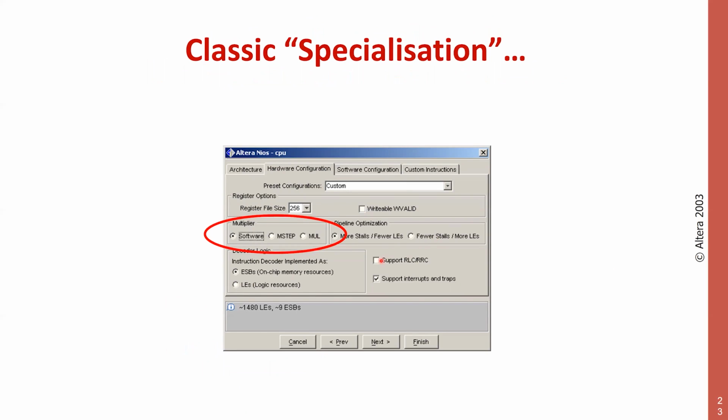And if you take, for instance, NIOS, one of these customizable processors that are meant for FPGAs, in the configuration windows inside the tool, you can say, I want to do multiplication in software, which essentially gives you the code from the beginning. It's very well possible that actually that piece of code I have taken from their library, because then there will be a library in the Altera software that implements it in software. Or I implement this operation, or this operation, which is a normal multiplication, and this one is the intermediate. It's exactly what we have seen.